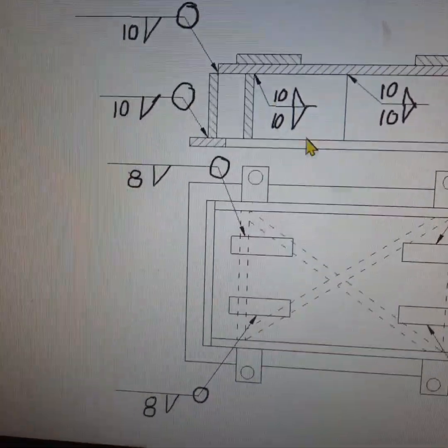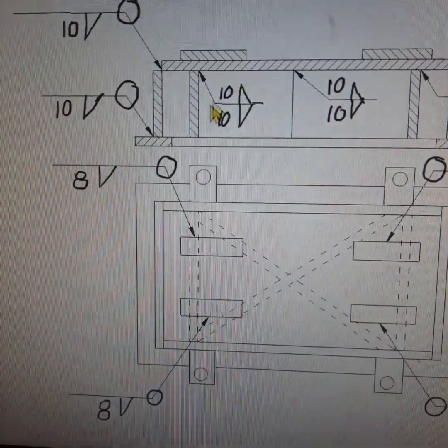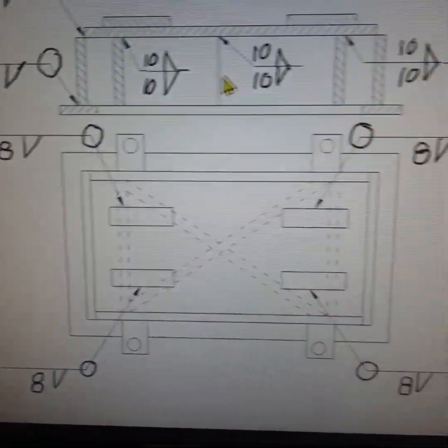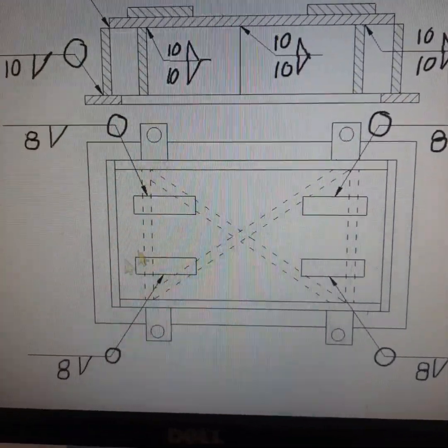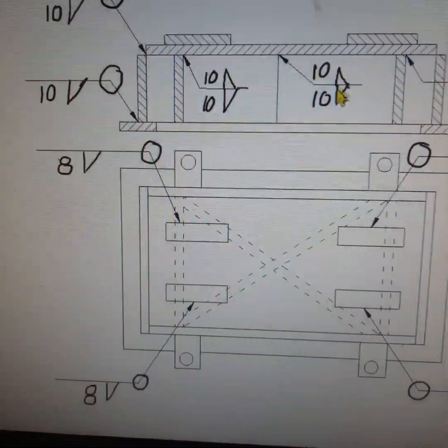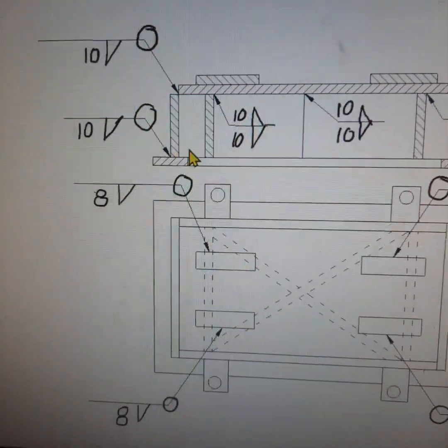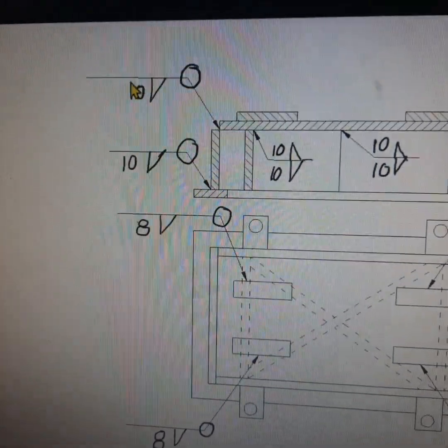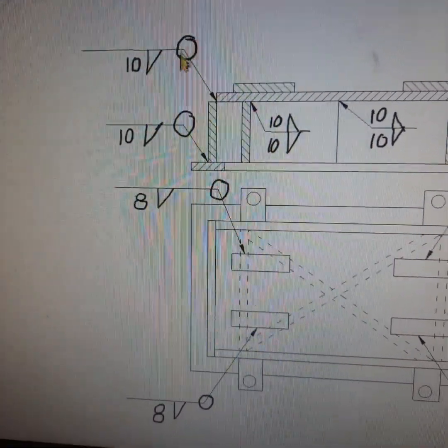Then once all the 4 plates are joined, there is a horizontal plate. Over the horizontal plate we provide the strengthening ribs using fillet weld of size 10 mm, diagonally placed as well as parallelly placed. Those things are shown in this diagram. Then once the horizontal plate is placed over the 4 vertical plates, it has to be joined using a fillet weld of size 10 mm. Welding is to be done on all the 4 sides, so weld all around.